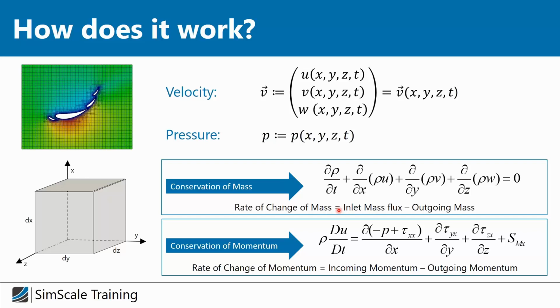First of all, CFD, or simulation in general, is just an assumption, and it will give us an approximate solution, not an exact solution. And the second fact, which is very related to the first one, is that the accuracy of your simulation results depends on how you set up the simulation. If you use very small elements, you will get a better resolution of your simulation results, the accuracy will increase, but at the same time, the computational effort will increase. And in the end, every time we're doing a simulation, it's a trade-off between accuracy and time.